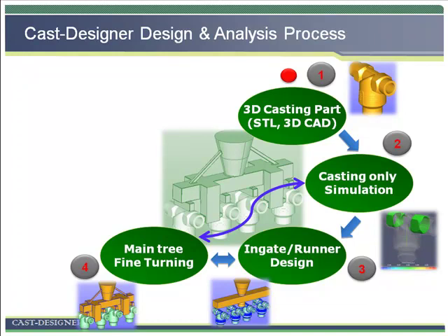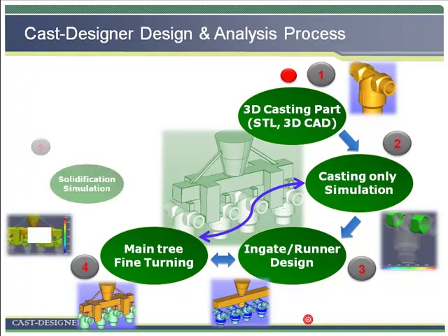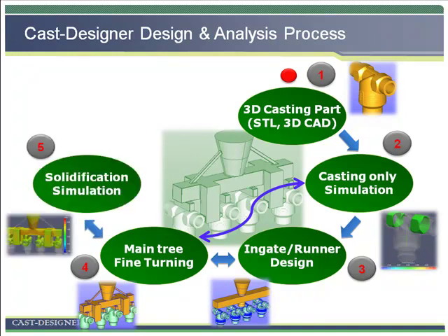With Cast-Designer's expert system, special for the smart design function, we can simply get a rough design very quickly. The system can calculate an optimized filling time and inner gate section area. Then, we can make some adjustment of the dimension and shape of the runner and pouring cup, since all design in Cast-Designer are parametric.